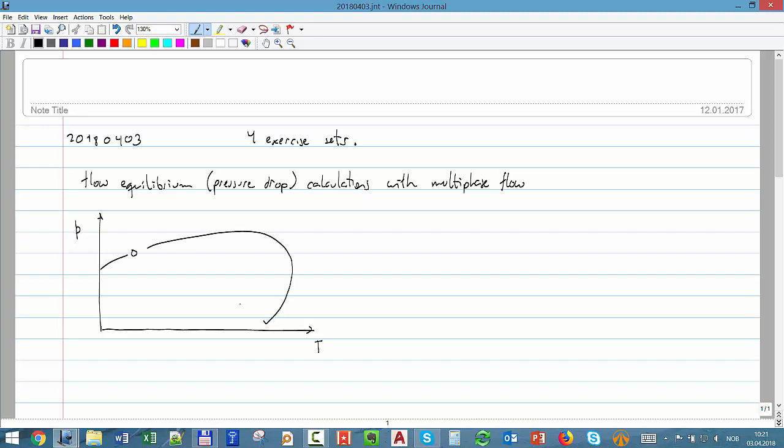remember in the reservoir, usually if it's undersaturated, we are someplace here, but when we flow through to the separator conditions, let's say that P separator is someplace here, the temperature decreases and also the pressure decreases. So up to here we can use all the single phase equations that you saw, but from this point down you'll have multi-phase flow, and you will see it in the wellbore.